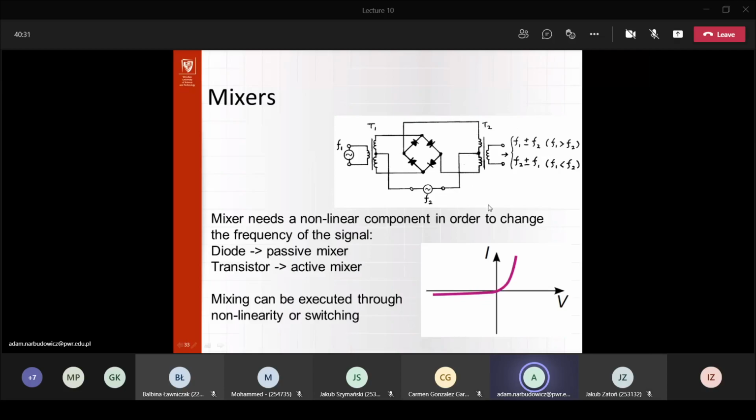It's not the best one, simply because those are passive diodes, so they don't allow any amplification of the signal. Typically you prefer transistors, but okay, that's the most simple you can get. What's important is that in this context, the diodes are put in the ring configuration, one after another.